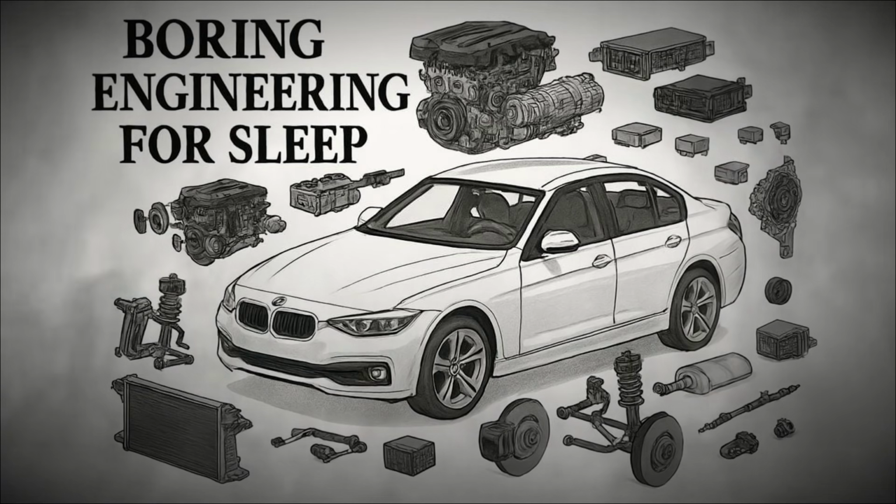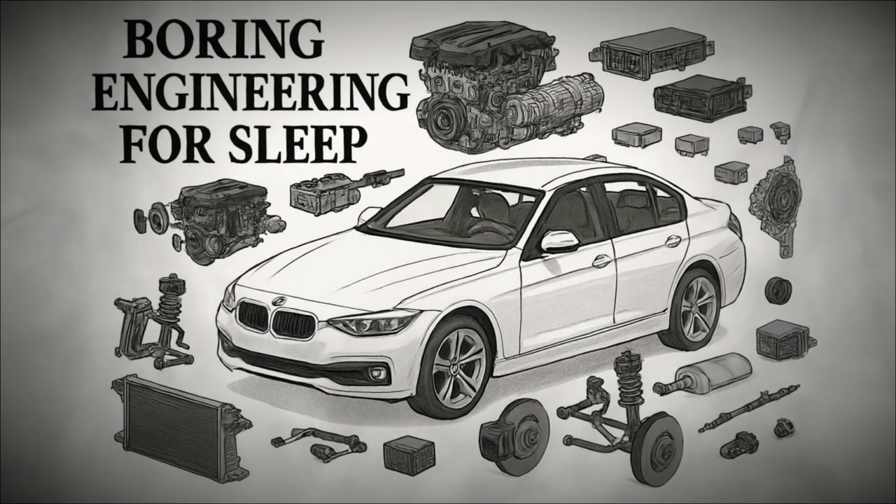Together, these three parts create a cycle in which the battery powers the starter to crank the engine. The alternator then recharges the battery and powers the car while running, and the system remains ready for the next start. Beyond these primary components, the electrical system also includes fuses, relays, and wiring harnesses that distribute power safely throughout the vehicle.